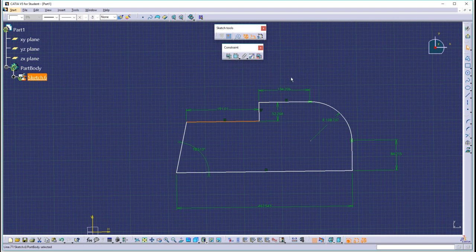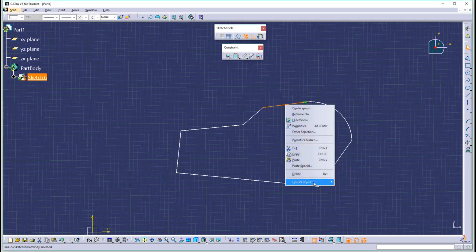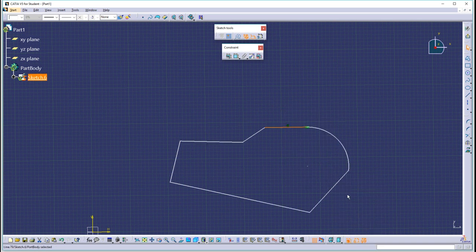Next, we're going to learn how to use the right click on your mouse to create constraints also. Okay, now let's look at using the right mouse button. Let's select an element. I want to make this horizontal. So I'll select it, right click, Object, Horizontal. And now I have a little H on there. And notice that this icon was on, so the H stays there permanently.